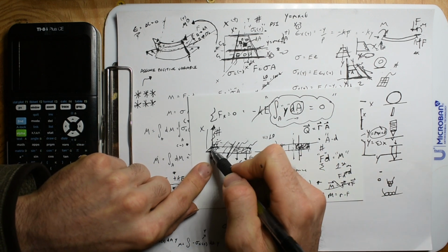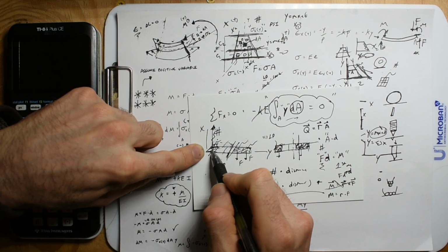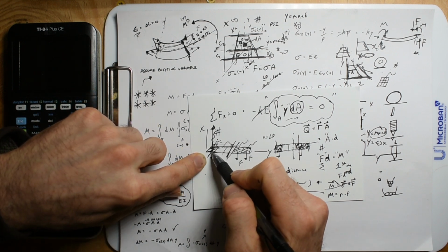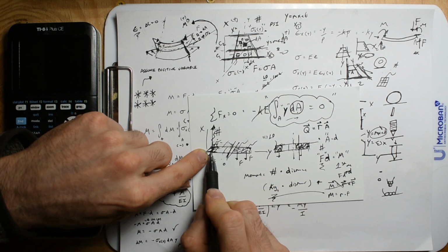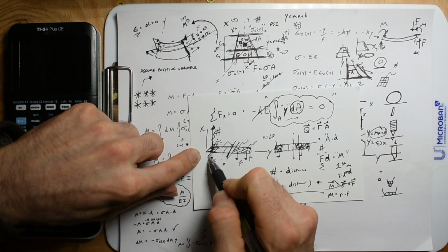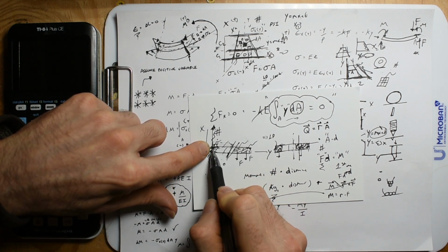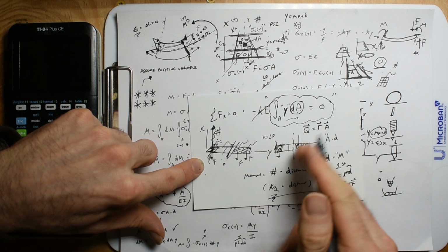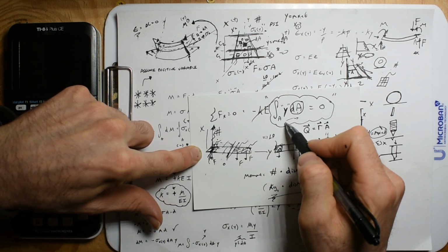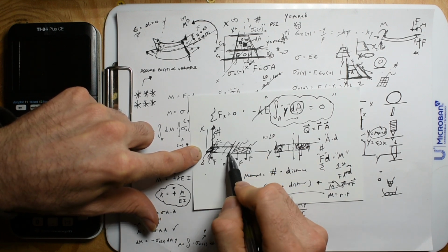Cool. Integration just means that, hey, if I have this chunk of area, could I measure from the middle? Well, yeah, if I measure from the middle, I should be measuring just that little strip of area. So that's where you have to do the integral, even though if you take all this area and then multiply it by the center, for first moments, you'll be just fine. Second moments, hell no. If you're going to square the distance, this area out here is way more punishing than the area right here.